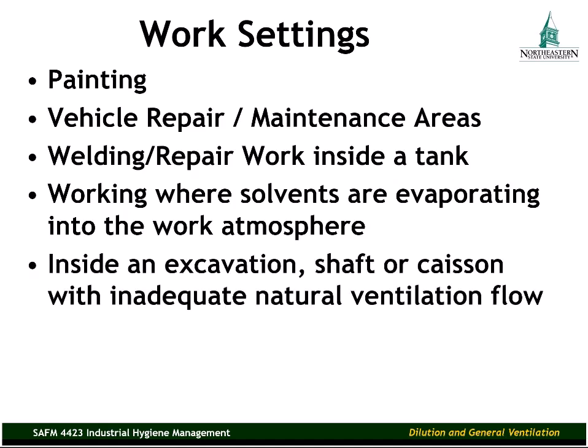An example where I've used dilution ventilation and also local exhaust ventilation, but really dilution ventilation most of the time is going to be adequate, is inside of an excavation, a shaft, or a caisson where there's an inadequate natural ventilation flow. One of the good things about construction and these types of contaminants that we've been talking about, a lot of construction is outdoors where you have natural ventilation going on, and that natural ventilation will take care of the problem a lot of the time.